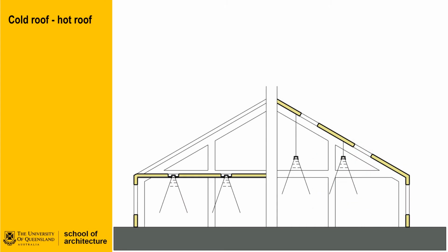The definition of inside and outside is also important when we consider roof voids. Architecturally, it is always great to express large open volumes, but we must be aware of the impact this will have in defining the envelope and the volume of conditioned space. Other aspects to consider also include the position of surfaces in relation to the external envelope. We need to consider what side of the envelope the surfacing sits, as well as recognizing the necessary safety clearances around heat-generating equipment, such as lighting fixtures.